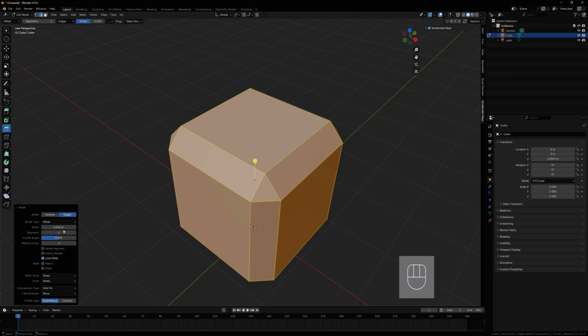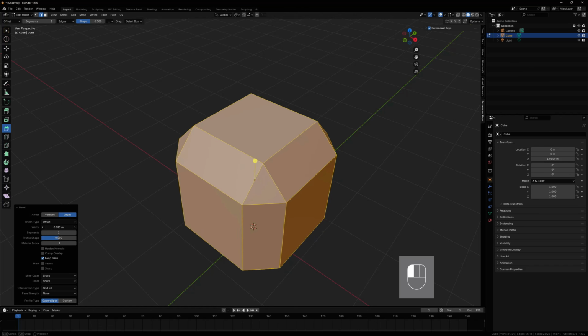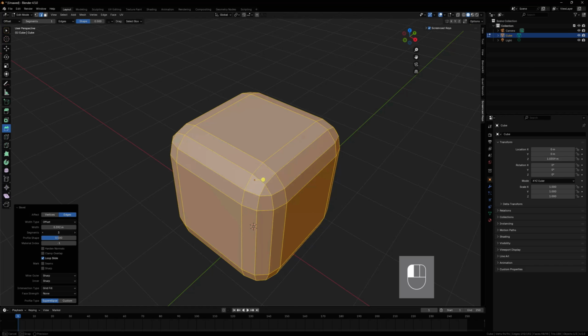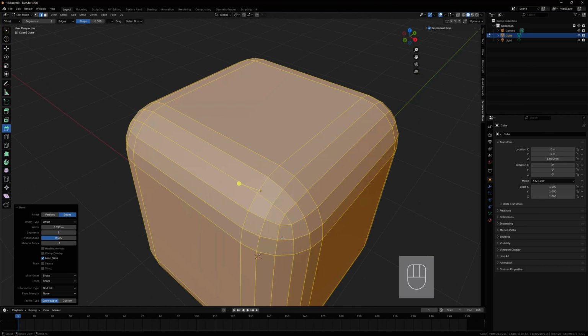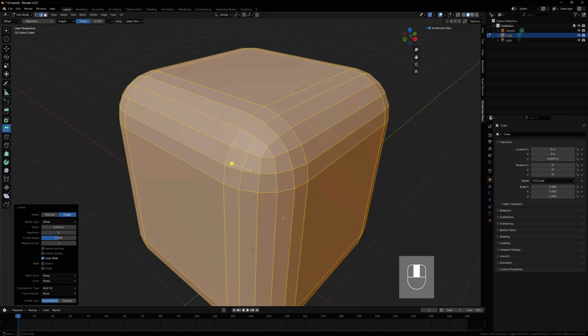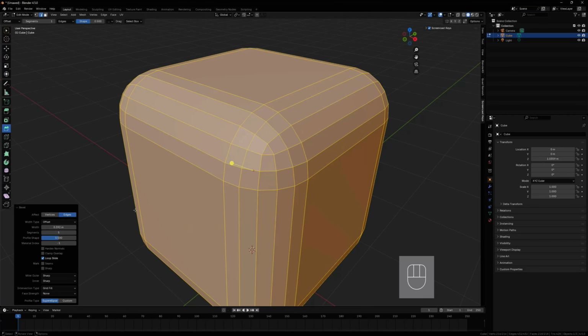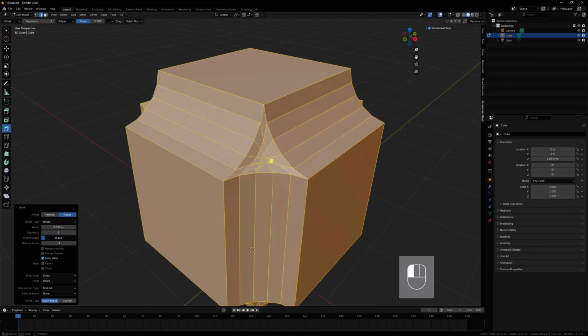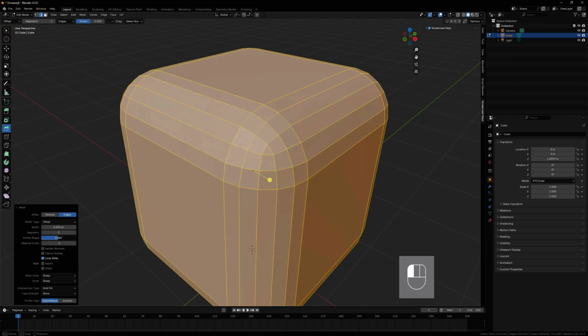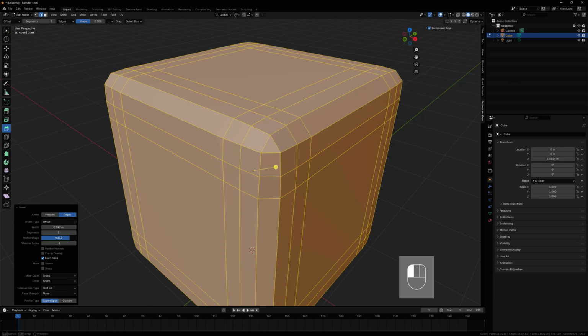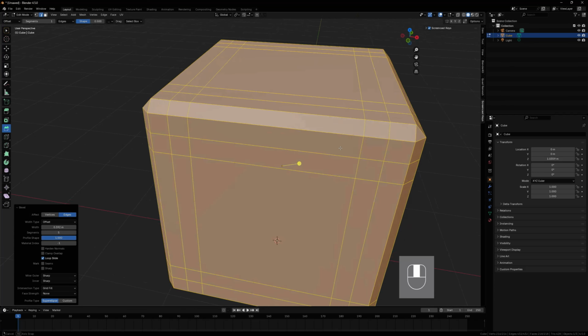From the top list, Affect controls whether the bevel applies to vertices or edges. Width controls the size of the beveled edges from the previous existing edge. Segments subdivide the width, creating a smoother transition. The profile shape controls the bevel's external transition from an internal 90-degree angle to an external 90-degree angle. Importantly, segments must be an even number for flat edges.